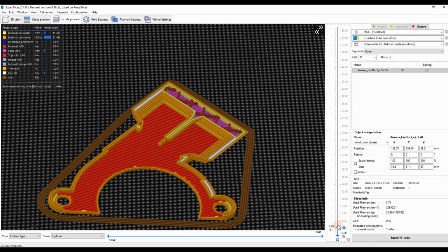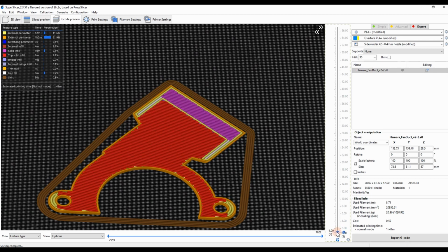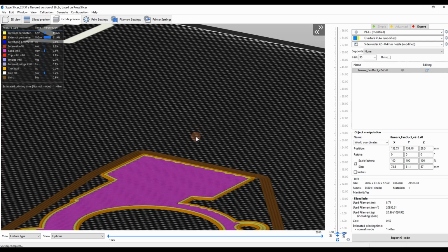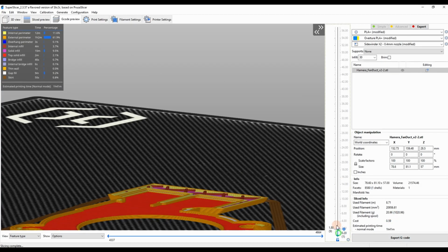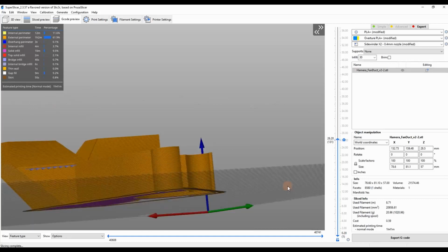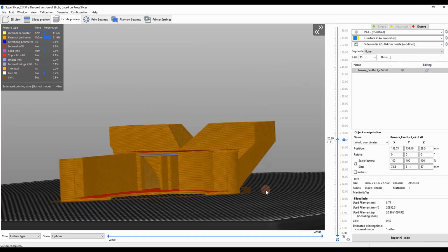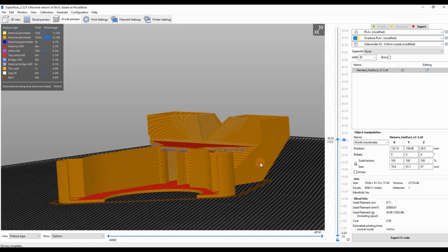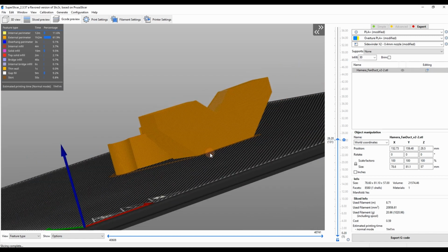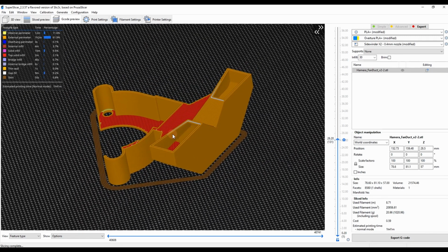And then you're going to get to top solid infill. So these are just all kind of differentiators that you can change the settings on individually by all these different line colors. Overhangs, we might have some here. Let's see. Nope, so they're not showing any overhangs, but if there were, they would be kind of a shaded blue color, along an angle depending on what settings you have. So I just don't have it where it's identifying any right now.